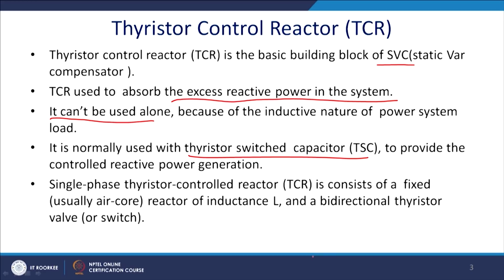So, we shall see why it alone is not competent enough to enhance the capability of the power transmission. We require the support of the TSC with the TCR to effectively utilize the power handling capability of the line.